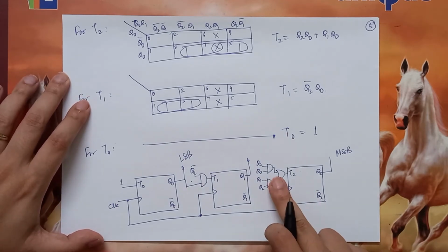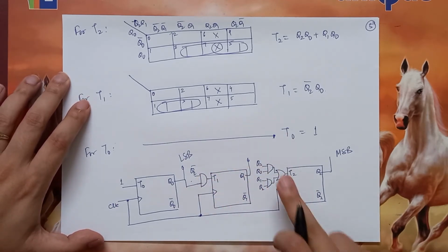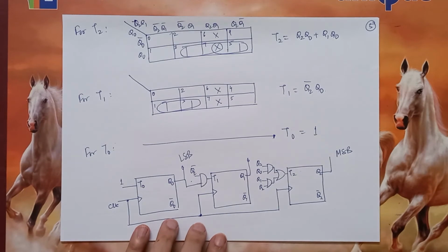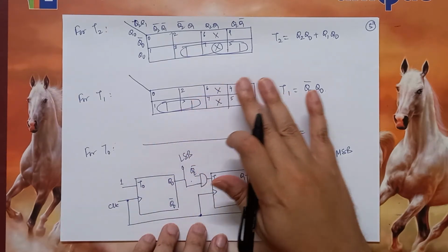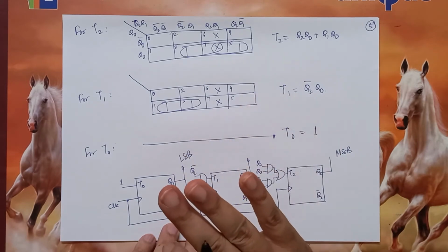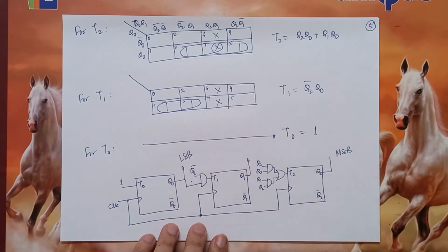But now what we see is that the number of additional gates required is just 4. Compare this with the earlier case where we were forcing 6 and 7 to go to 0. We needed 7 or 8 gates. So therefore, in this technique, we are taking the states 6 and 7, and the next state we are assigning them is don't cares. So with this, we have reduced the additional circuit requirement.